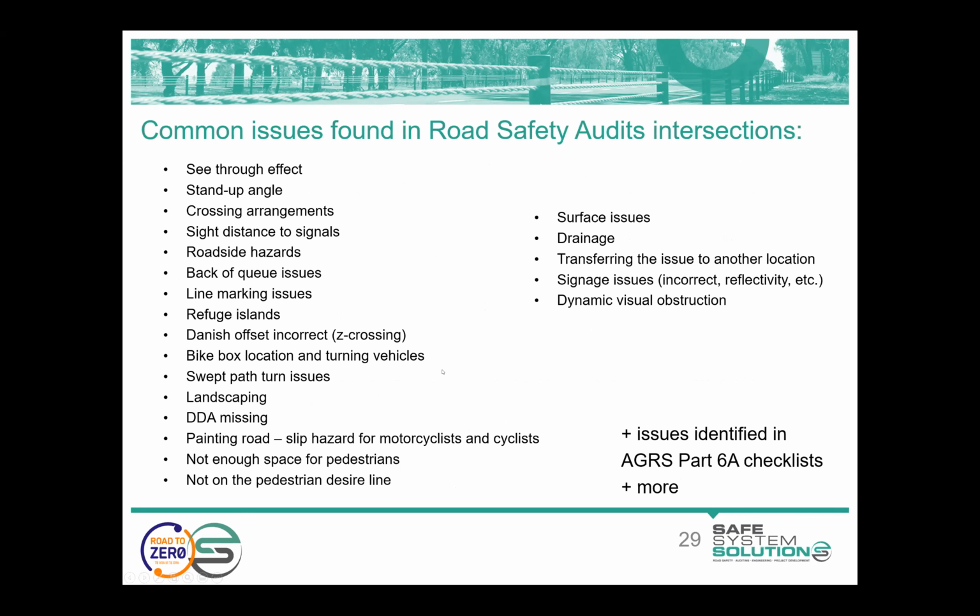Jamie, Mark's provided a little more clarification and done a great job of sharing it with all attendees, but just to round out the sight distance discussions. So to clarify, SISD is the same as SSD, stopping sight distance, but has a bit at the front of the formula, DT times V divided by 3.6, where DT is decision time, observation time 3 seconds plus reaction time, which is in part 3 there.